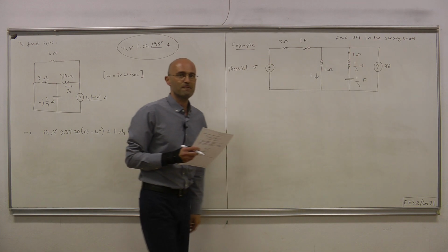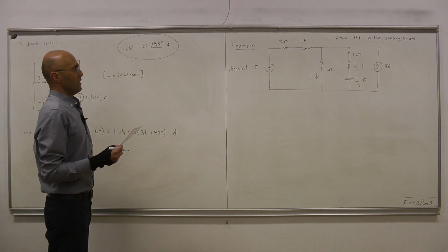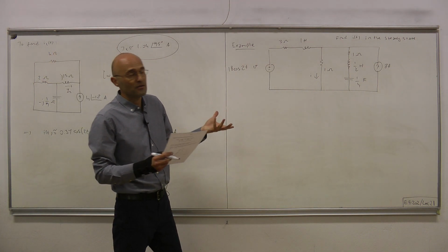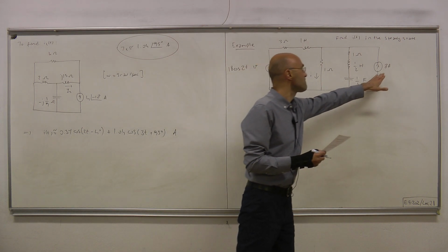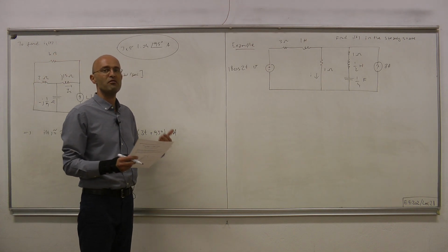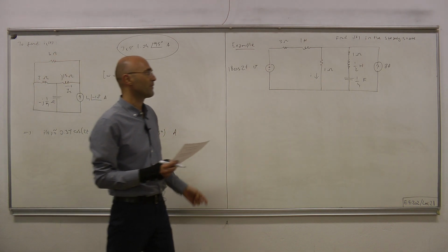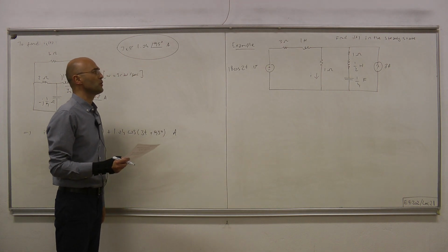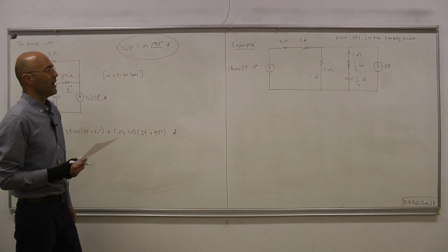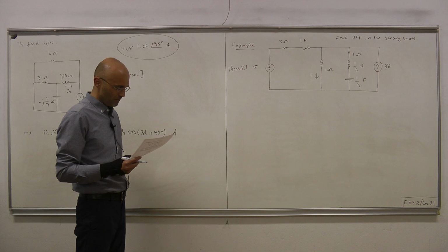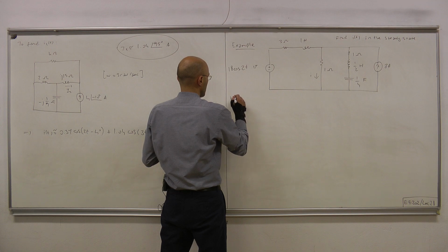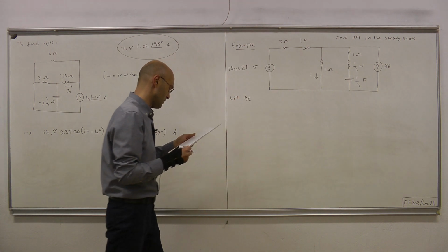And that's what we call the current in the steady state. Okay, again, we have two sources, and from the mathematical point of view, we have two sinusoidal sources at different frequencies, because a DC input can be considered as a sinusoidal input with frequency 0 radians per second. Again, what we're going to do is consider one source at a time, which we can, because the circuit is LTI, and then apply superposition. So let's begin by killing the DC source. Kill the 8 amp current source.